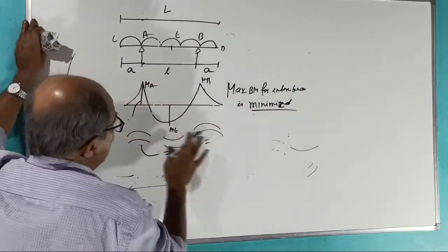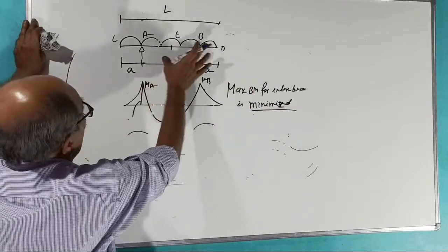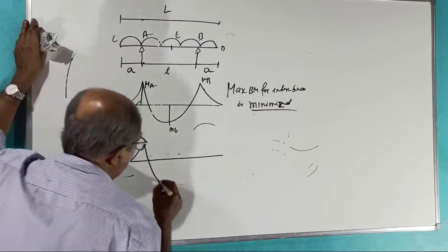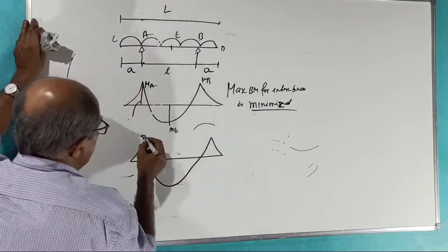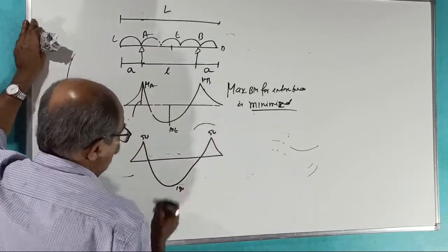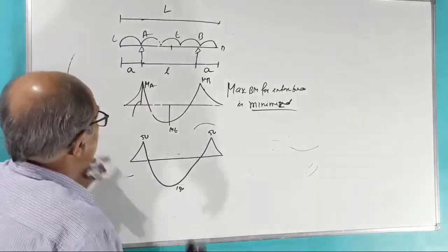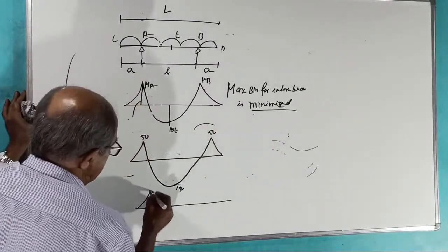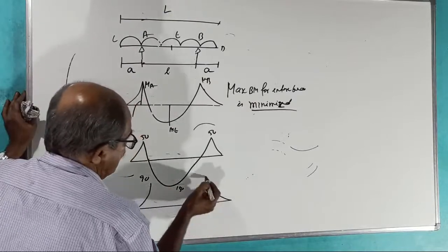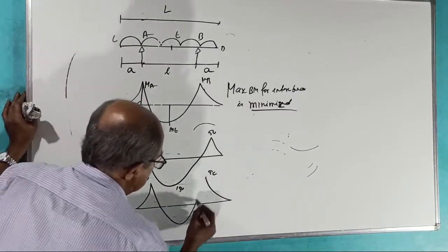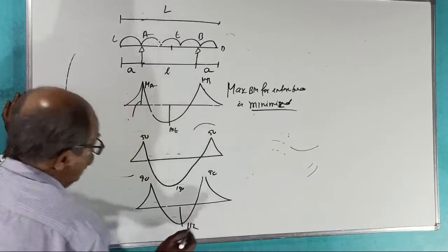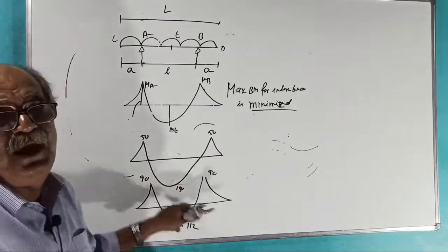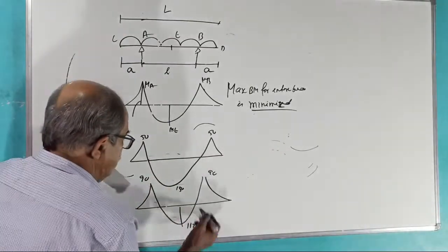Now I will give an example. If the overhang is very small, B and D come out like this: 50, 50, and 150. A high BM of 150. Now if I increase the overhang, the BMD can be made 90, 90 and say 112. That is better, because earlier you should design for the highest BM of 150, and now your highest BM is 112.